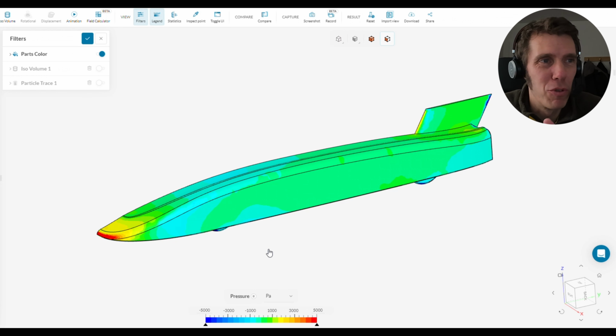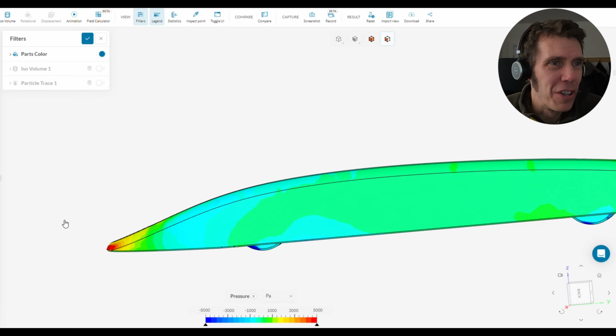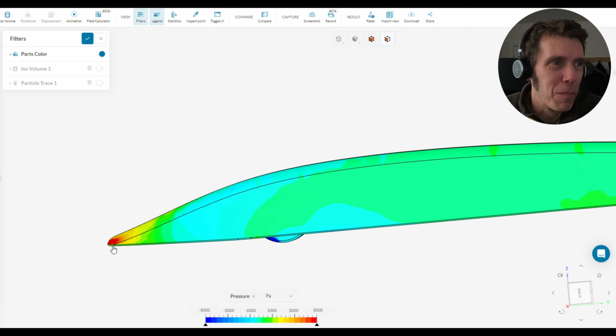So I was able to reduce the width and length of the chassis, which correspondingly made the body shell a little bit smaller. And because of that frontal area reduction, the CDA value, which I mentioned on my previous video, is very important. That goes down a little bit. So that was a nice optimization. I also decided to compromise my front raised ride height that I mentioned a minute ago by 5mm. So it's still got 15mm clearance at the front in static condition.